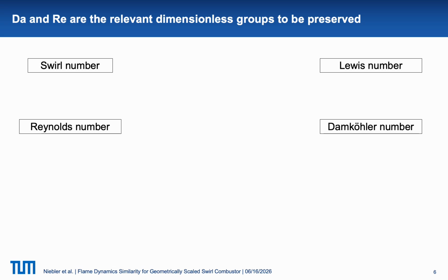what happens to our operating conditions, so basically the velocity or the equivalence ratio, to name maybe the most important ones in this case. So we look at the non-dimensional numbers. On the flow perspective, we have the swirl number and the Reynolds number as probably the most prominent of the group. They define how the flow evolves and how the swirl structures, namely the vortex breakup or the recirculation bubble, appear and change if we change the swirl number and the Reynolds number.